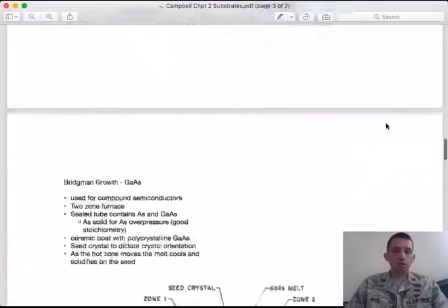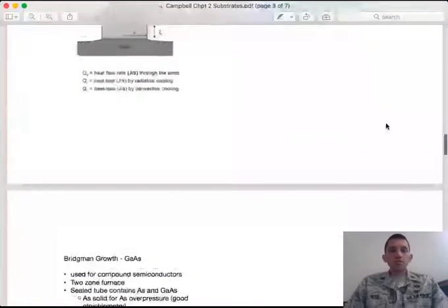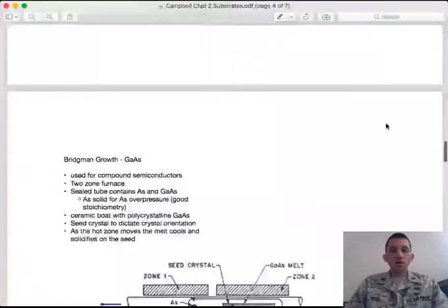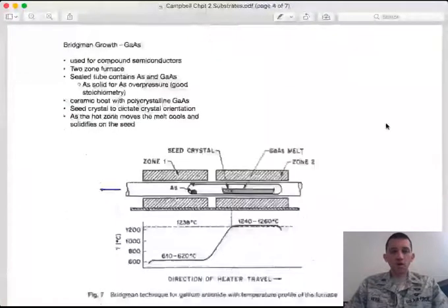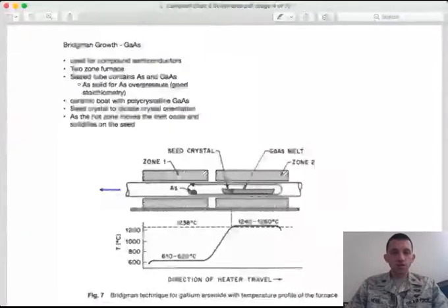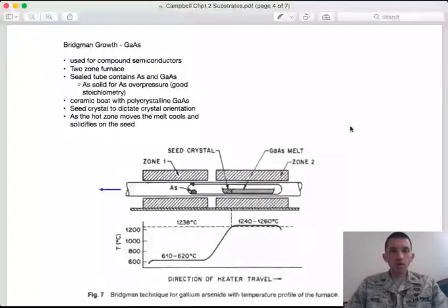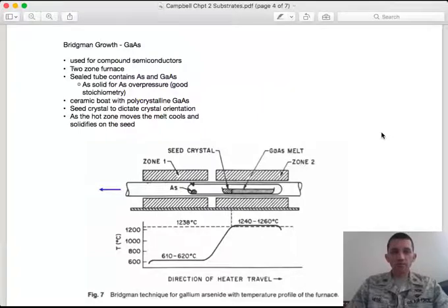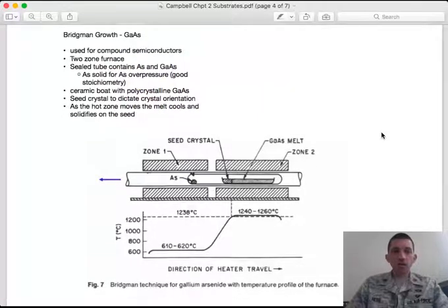yeah, okay. So Czochralski works very well for silicon, and that's one of the reasons why it's used so much. For compound semiconductors, right? For example, gallium arsenide, that's a 3-5 material. Czochralski is used in a different way, and it's given a different name, right?